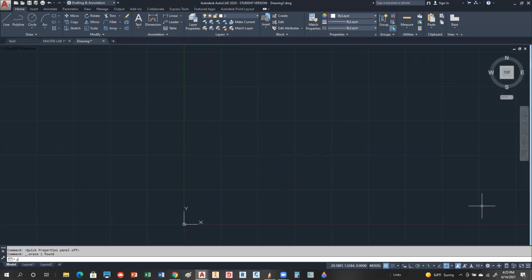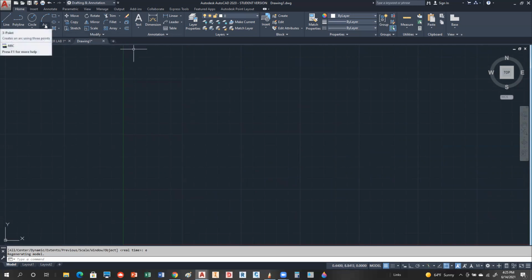Okay, so the other option that's kind of interesting is the arc. Now, the arc option in Polyline is just as hard as the arc option over here, with the start, center, end, and all that kind of stuff. You have that same kind of thing. The one thing that is kind of cool about the polyline arcs, though, is that they're automatically tangent.